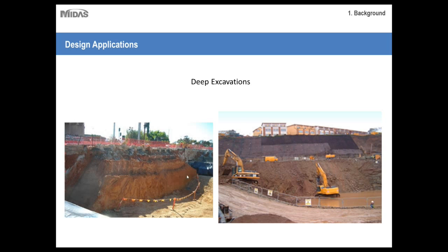But depending on the type of soil, the soil to the left here is actually very clay soil. As you can see, it can stand very firm on its own as long as it's not too high. So that's another important design consideration: the type of soil that you're excavating into.